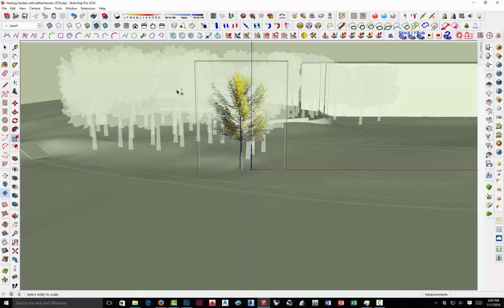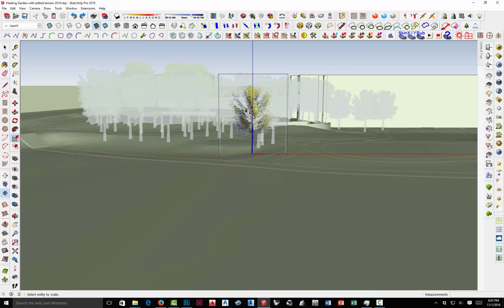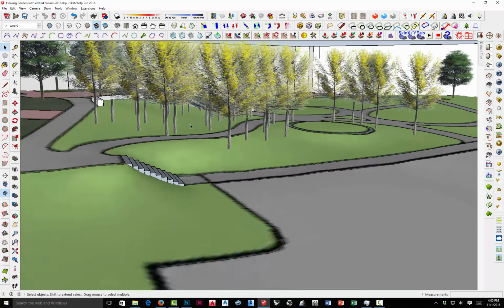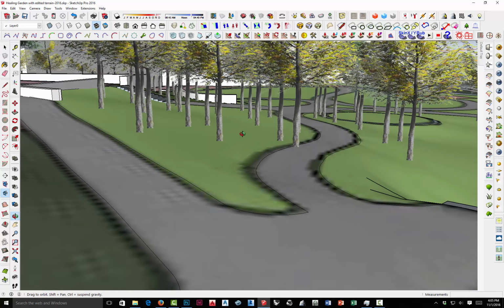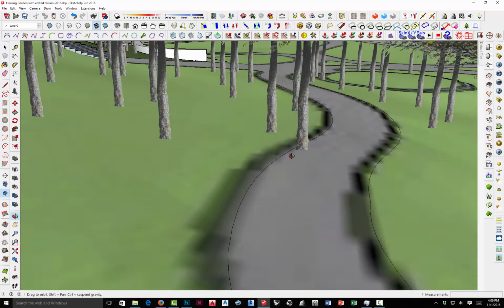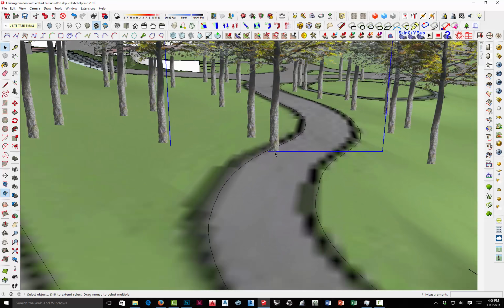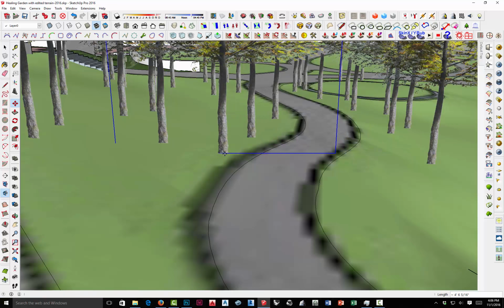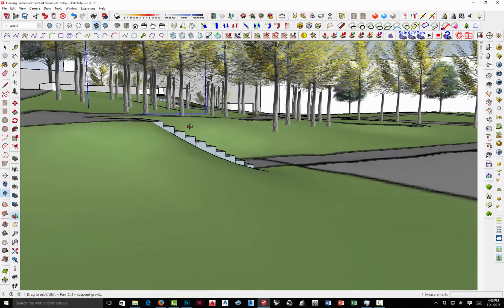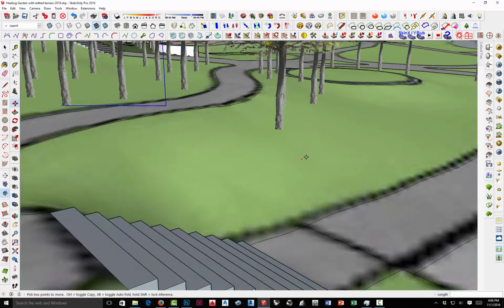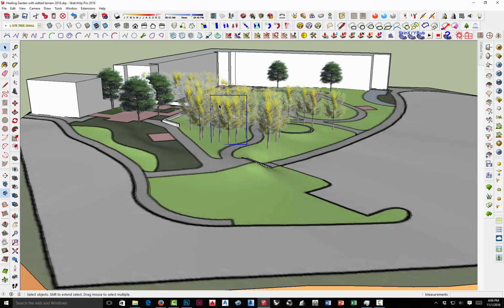So that's why I scaled it vertically, then I did the control key and scaled it horizontally. If you scale it in one dimension at a time, it keeps the center exactly where it's supposed to be. And again, I can check this and say, yeah, that looks pretty good. Now, if you see something like this, that instance, maybe the way it was lined up is a little off. So just pick that, slide it over, drop it into there, and make whatever adjustments. But you can see they all do a pretty nice job of being connected to the landform. They're not floating out there in space somewhere.